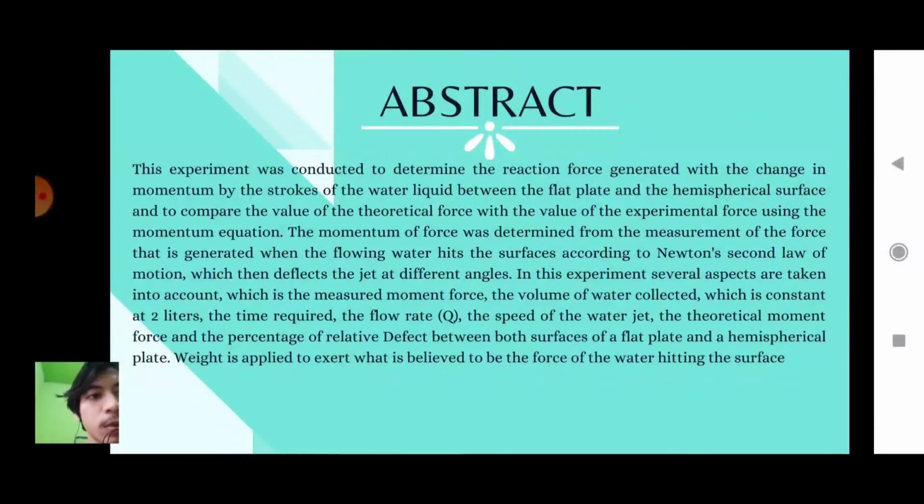The momentum of force was determined from the measurement of the force that is generated when the flowing water hits the surfaces according to Newton's second law of motion, which then deflects the jet at different angles.